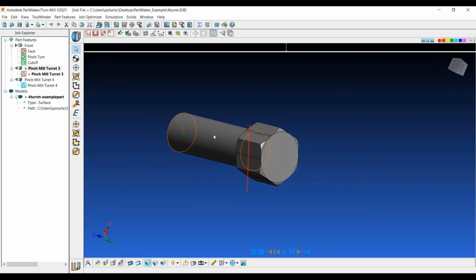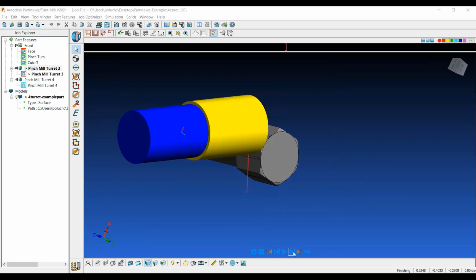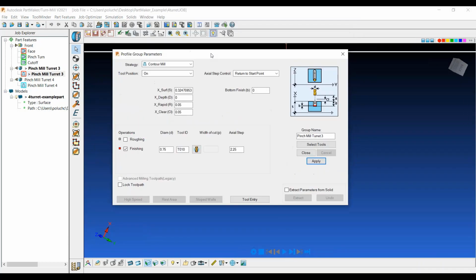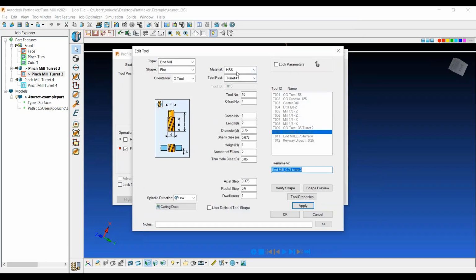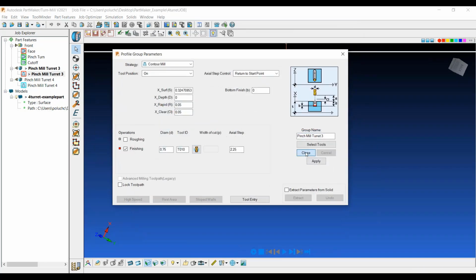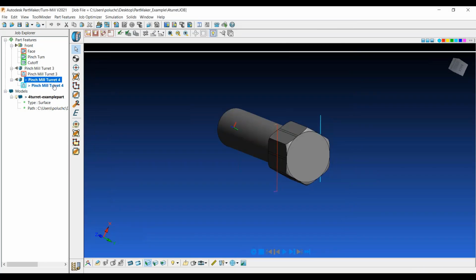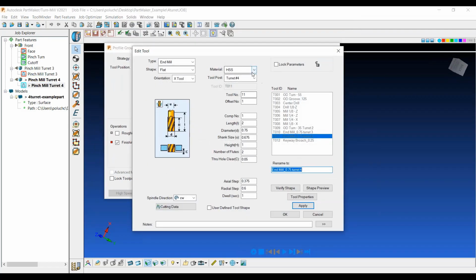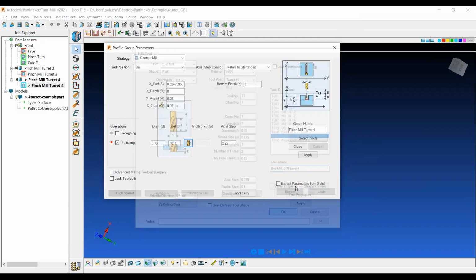Now these operations themselves are fairly simple. It's just a line going straight across the part, but because in the tools themselves, we've chosen one of them being on turret 3, and then let's go to the next face window here, 180 degrees from it, we're using a tool on turret 4. So tool selection is really key here in getting that set up properly.